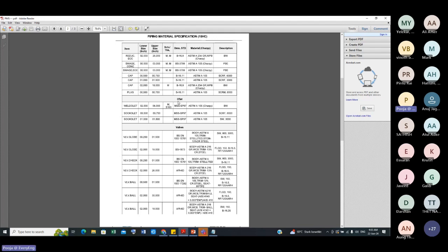That is why we prepare another document which is called a VMS, valve material specification, or sometimes we just prepare some data sheets. The terminology changes from company to company, but this is the general philosophy. Again, the general philosophy up to 1.5 inch is to use socket welded end valves. Then for bigger sizes, we can use the rated, that is class 150 valves.